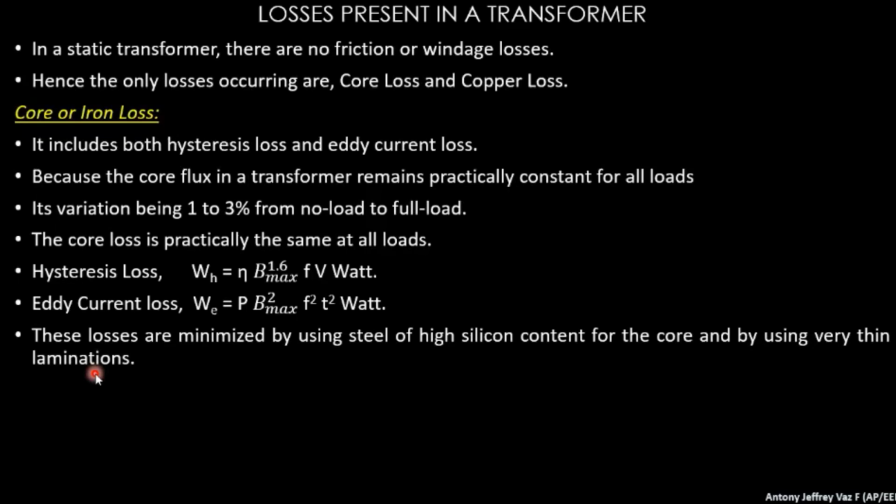We have discussed several topics about lamination from the starting of this class. If you have a very thin section of metal, then the eddy current loss is less, whereas if you have a single solid piece of metal, then the eddy current loss is high. To make the eddy current loss minimum, solid metal is cut into several pieces, and thin laminations are made, and all these thin laminations are riveted together with the help of a rivet.